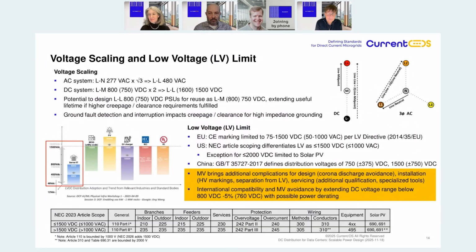as we look at where we are today versus where the trajectory of things may be tomorrow, and the extremely high roof line that you saw of where the power for the data center rack can go, even beyond the megawatt level, it's helpful to consider that with an AC system, typically you're increasing voltage by a factor of √3 between line to neutral versus line to line.